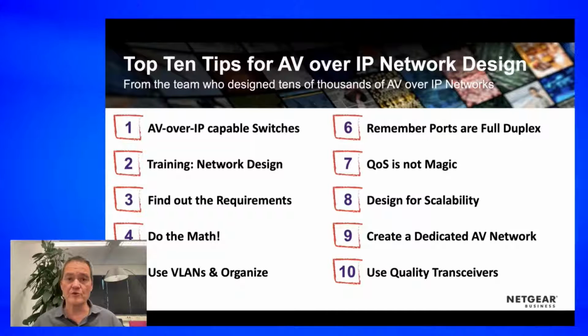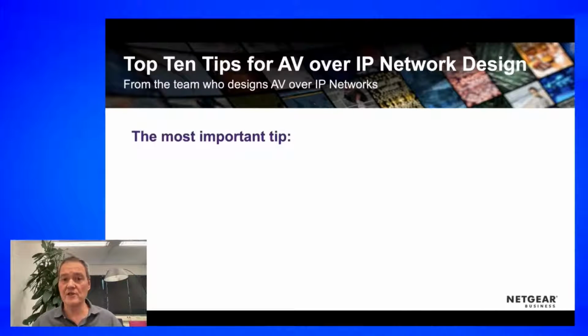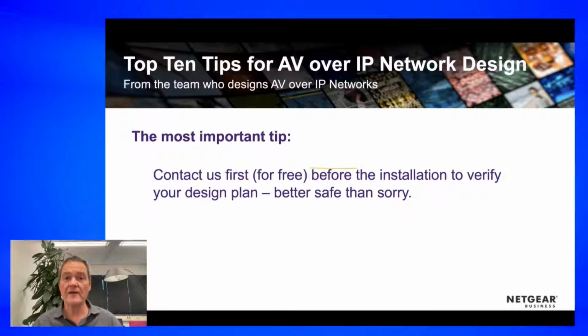Design for scale, not for today, but also for tomorrow. Create a dedicated AV network. Don't mix AV over IP with data and control, that ends in tears. You don't have to buy extra switches. Just make sure that the AV is handled only by switches done for AV. And finally, use quality transceivers so it doesn't break when you go from a switch to a fiber cable and use an inferior module. Most important tip, however, is to consult us before you start at